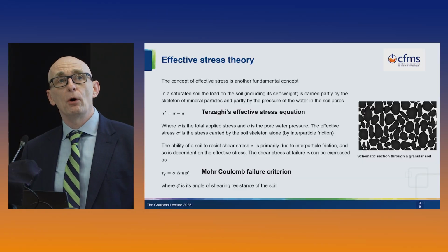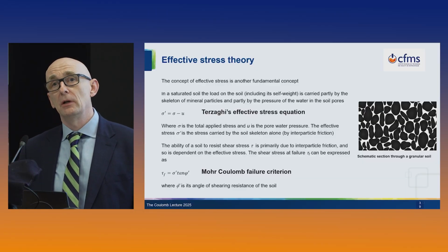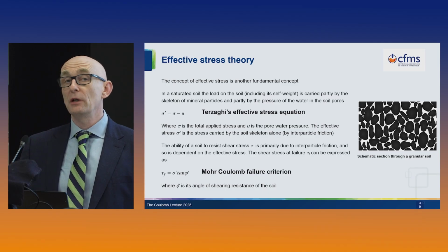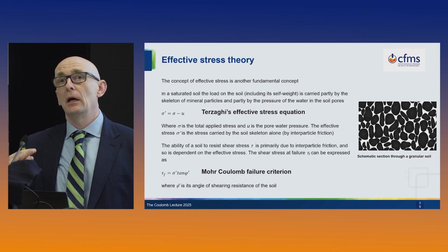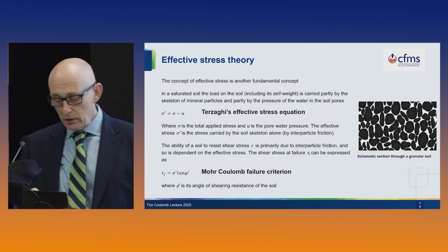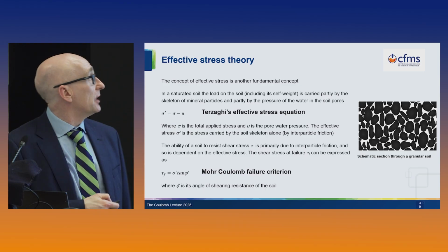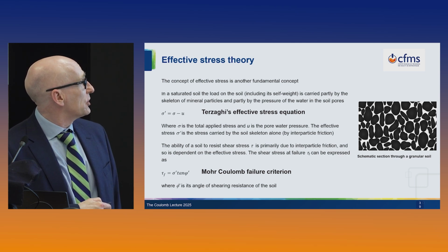So in very simple terms, if we lower the groundwater level, we're going to reduce the pore water pressure, and that's going to increase the stress on the soil particles themselves. Conversely, if by some means we raise the groundwater level, that's going to increase the pore water pressure, and that's going to reduce the load on the soil. But then the additional complication or sophistication is that the effective stress will actually affect the soil strength.